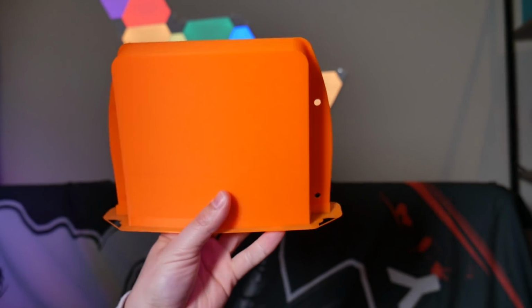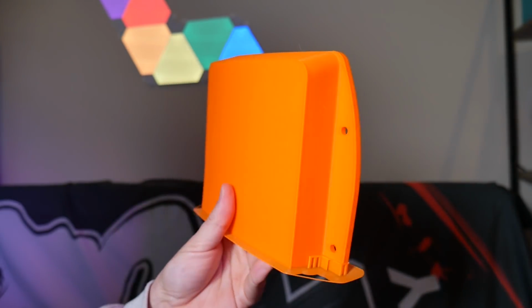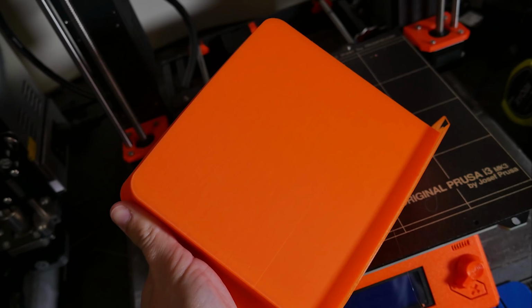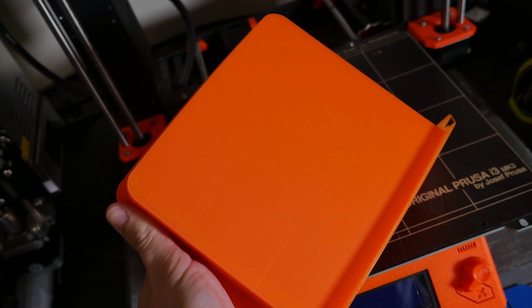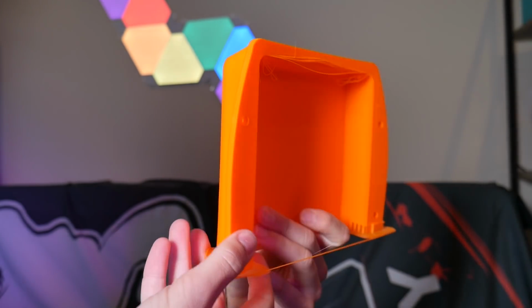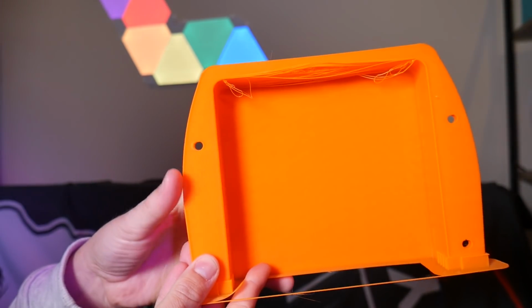I also took this opportunity to move my support enforcers down a bit so that first hole wasn't being filled with support, which I did mention in the slicing settings, you don't need that. So this is the next attempt. I did run out of the blue filament at this point, so I used an orange, and the part stuck down perfectly, printed really well until it got to that bridge, and that bridge is super messy.